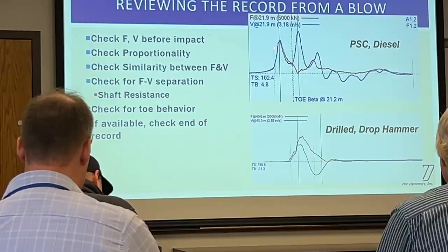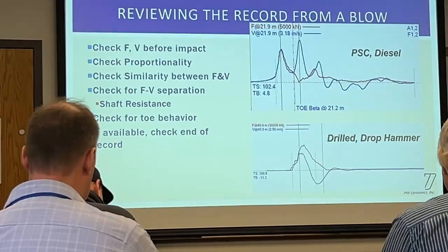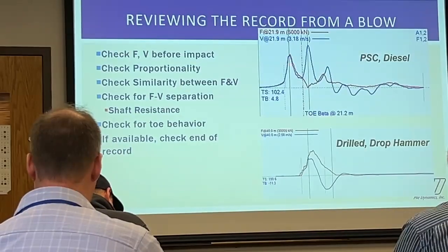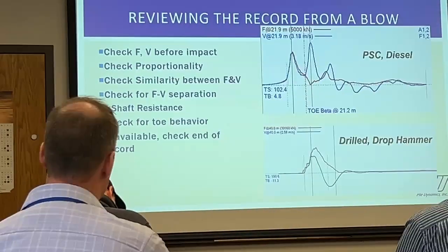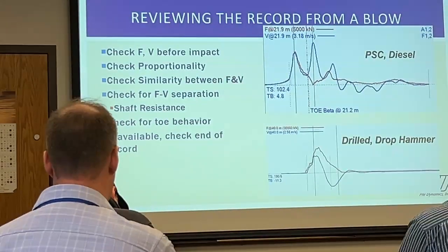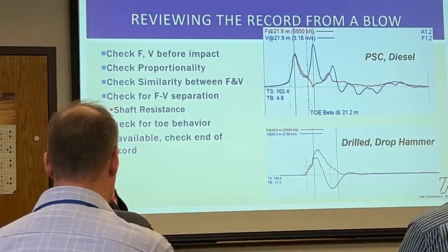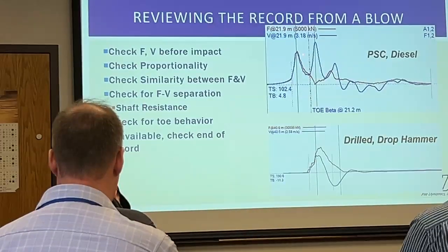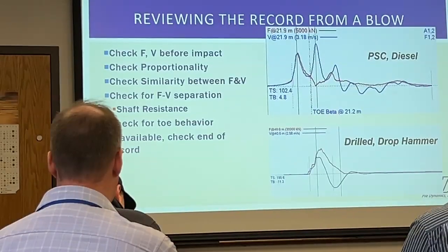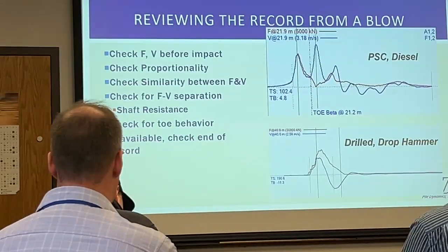But if we take a look at our pre-stressed concrete pile, we still see that those impacts are a little wider than what we were seeing for the steel piles, because they're cushioned with additional plywood. As that cushion stiffens, it becomes a sharper impact, but initially it also has this kind of wide pulse that we would expect.